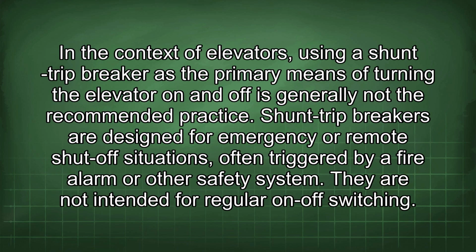In the context of elevators, using a shunt-trip breaker as the primary means of turning the elevator on and off is generally not the recommended practice. Shunt-trip breakers are designed for emergency or remote shut-off situations, often triggered by a fire alarm or other safety system. They are not intended for regular on-off switching.